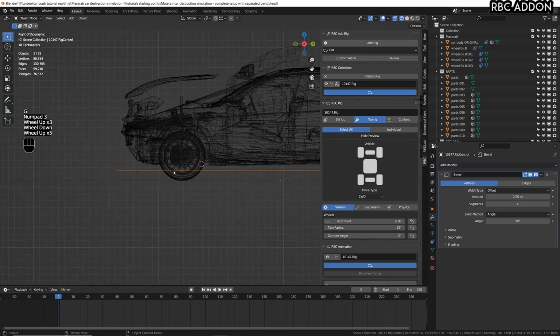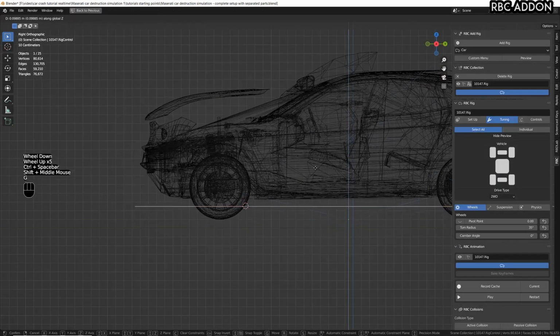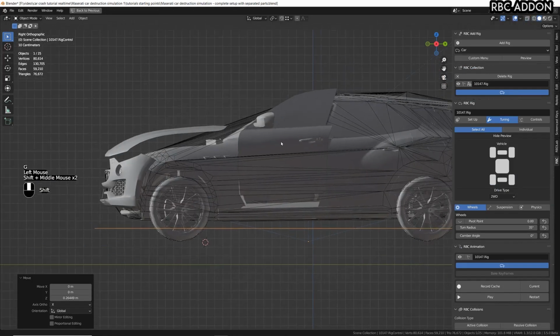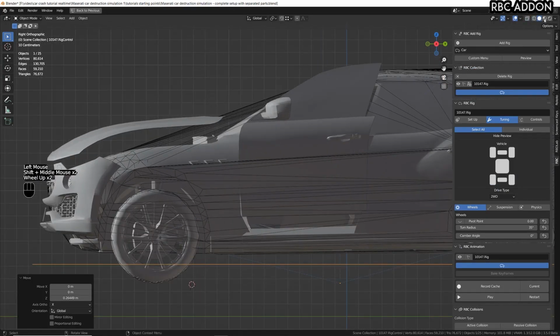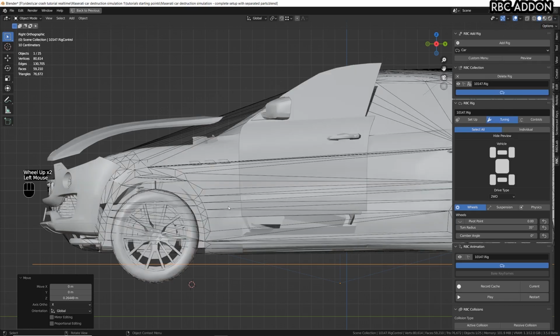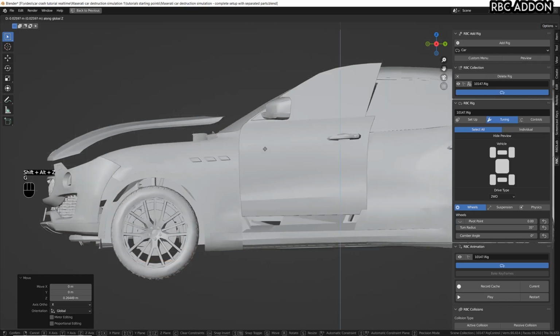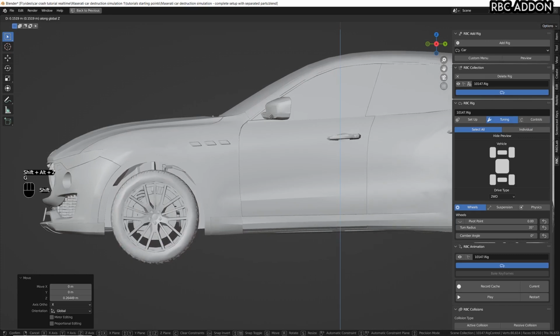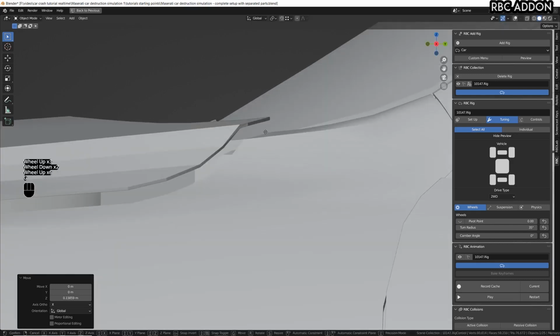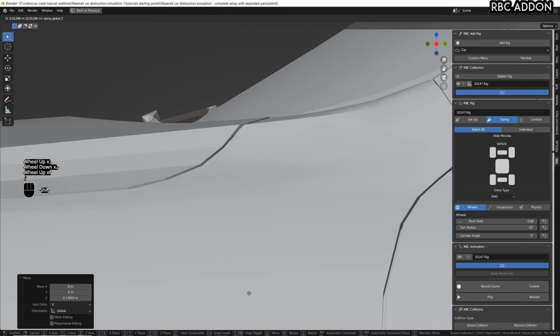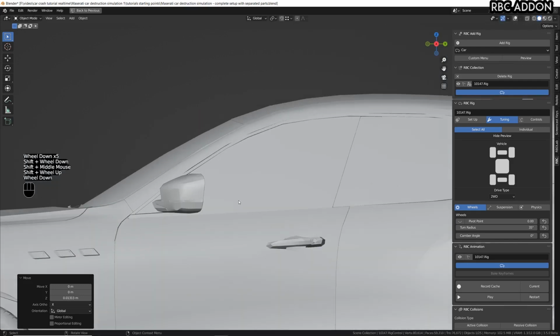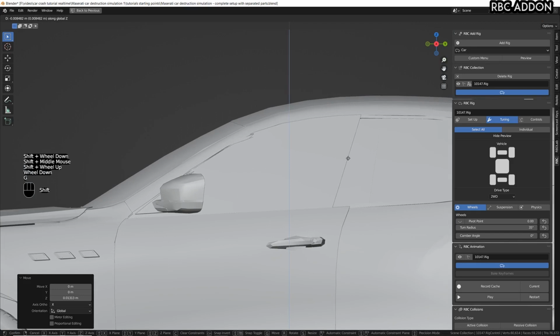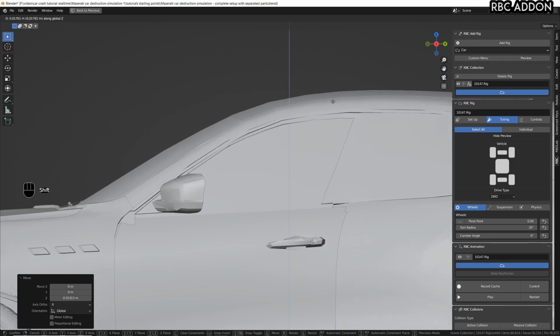So I'm gonna take this and move it up by pressing G and Z until everything is aligned again. For this purpose, I'm going to turn off the rotation of the specular light so I can see better what's going on. And so G and Z, until they align perfectly again. It's just a matter of moving in the perfect vertical direction, by the way, not in other directions. For example, from here, I can see that they are not aligned. Let's see the doors, G and Z, and it would be something like this. Okay, there we go, a little bit lower. There we go. I think I got the point.